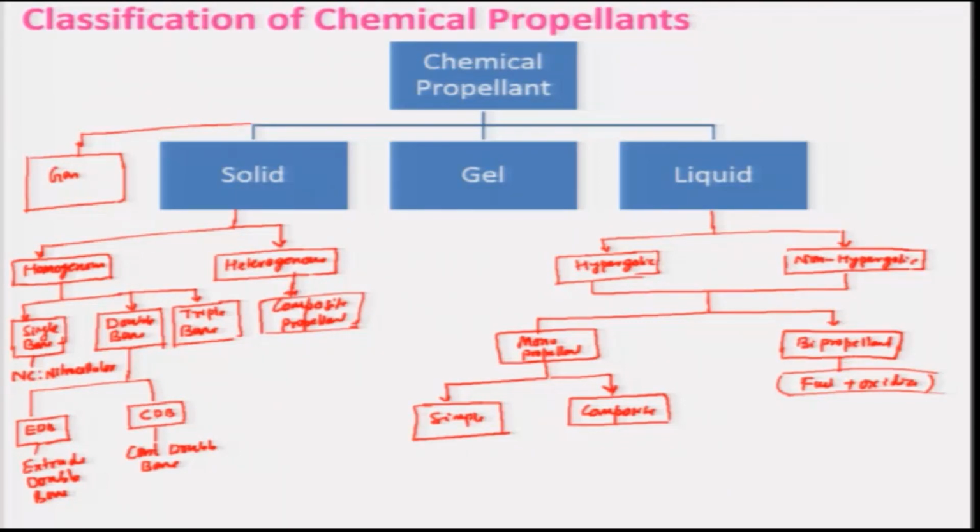Keep in mind that depending on this liquid, we can have various kinds of gel propellants, and gel propellant is not being used in the regular flights. However, a lot of research is going on for the gel propellants, as it is advantageous over the liquid propellant, and it is envisaged that one can get a higher specific impulse provided we load the gel with metal powders, such that a higher ISP can be obtained.